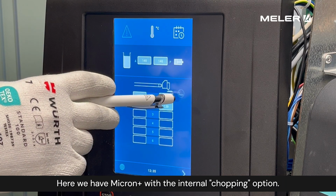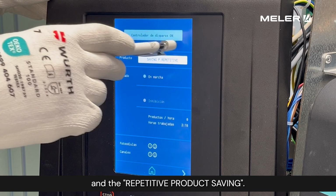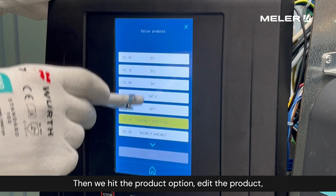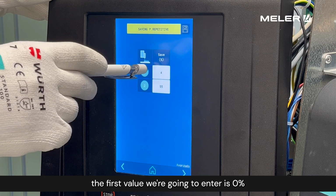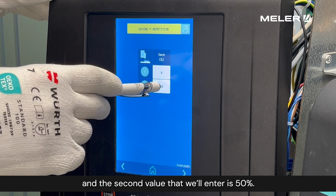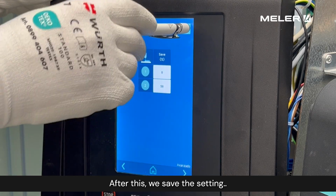Here we have a Micron Plus with the internal chopping option. If we click it, we access the shot control and the repetitive product saving. Then we hit the product option, edit the product, and within that product editing, the first value we're going to enter is 0%, and the second value that we'll enter is 50%. After this, we save the setting.